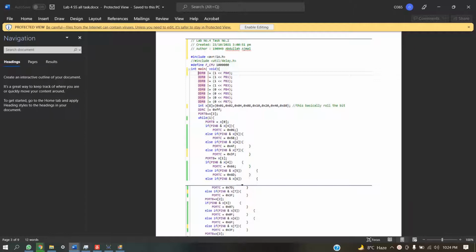Embedded system. So basically, what is the heading of lab number 4? The heading of lab number 4 is the introduction of implementation of hex keypad with 7 segment LED display. So basically, what is 7 segment LED display? 7 segment LED display is a complete package consisting of 7 LEDs representing digits, and the combination of LEDs represents digits from 0 to F, which means 0 to 15.